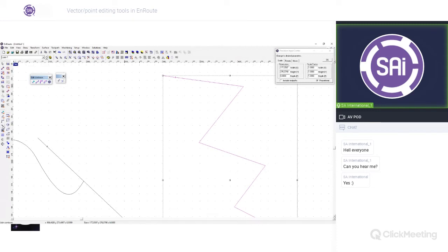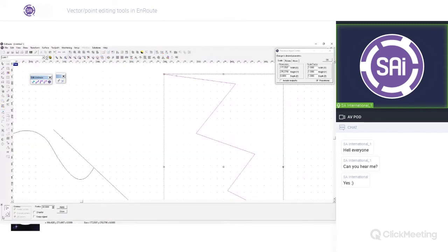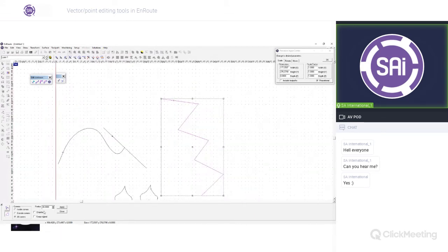You also have the possibility to do that for the entire contour, and here you can select to do that for the inside corners, the outside corners, or all corners. If we select the contour, you'll see the inside corners are the corners to the right hand side. So this is the direction that the contour follows. And the outside corners will be on the left hand side here. Or you can simply choose to do so on each corner.